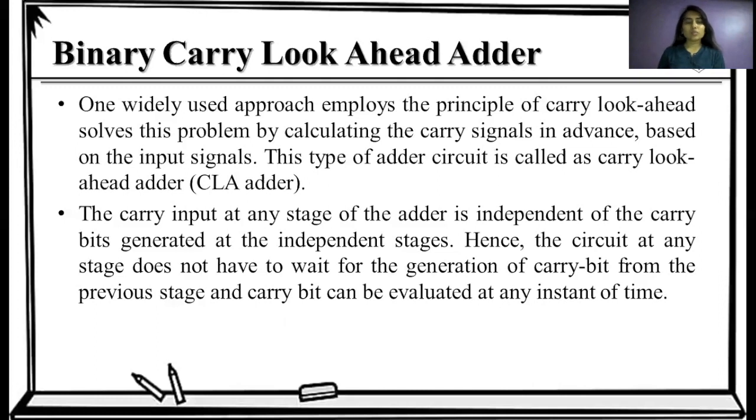The carry input at any stage of the adder is independent of the carry bits generated at the previous stages. Hence, the circuit at any stage does not have to wait for the generation of the carry bit from the previous stage, and the carry bit can be evaluated at any instant of time.